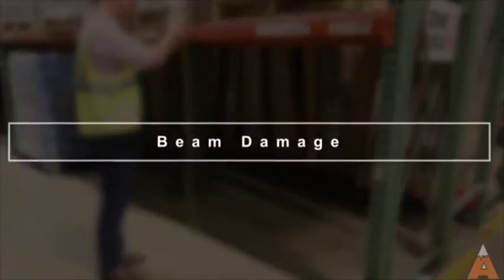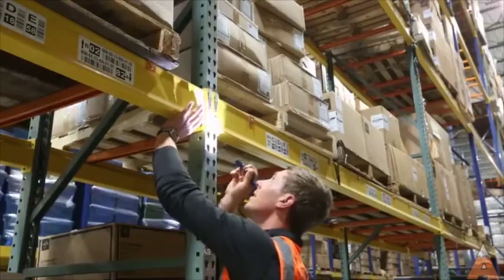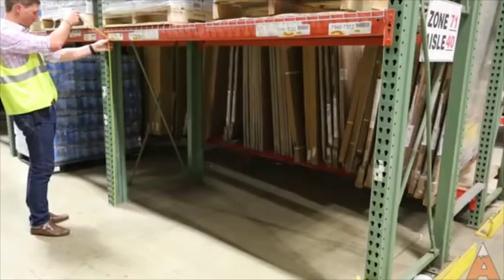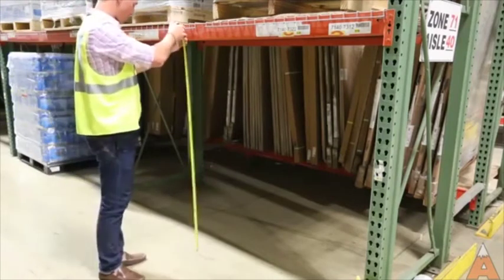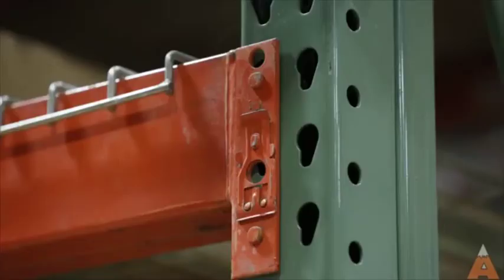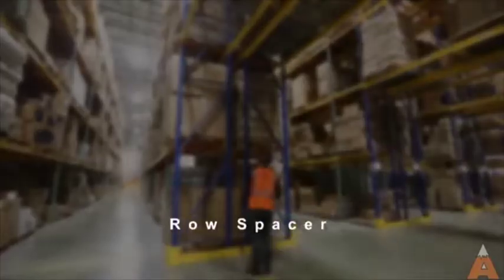Proper beam inspection requires more than just checking for equipment strikes and damage. You must record any damage that causes deflection of greater than a ½ inch. Also, check for overloaded beams by measuring allowable beam deflection. This is determined by dividing the length of the beam by 180. If the beam is deflected down by more than that number, it is overloaded. Also, be sure to record missing or damaged safety pin connectors and tears in the beam.